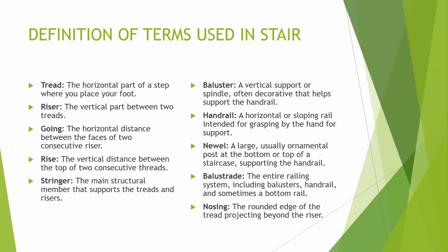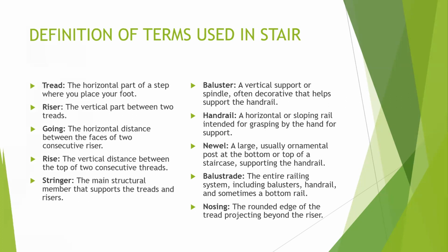There's something called a nosing, okay? That is the rounded edge of the tread projecting beyond the riser. When you look at some steps, you discover that there are some stairs where the tread is going to project a bit beyond the riser. You understand? It can be as low as just 25 mm and 50 mm. So that rounded edge of the tread projecting beyond the riser is what is called a nosing.